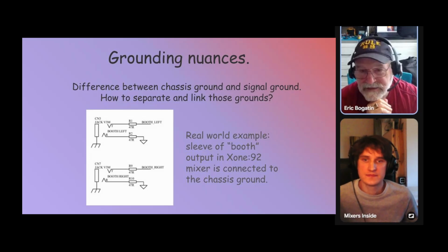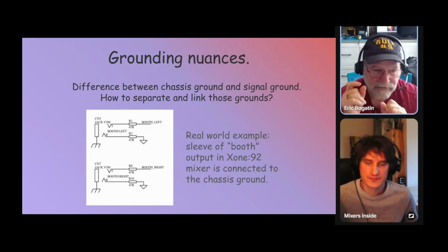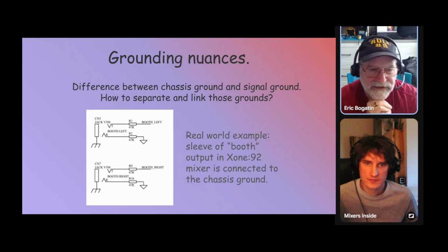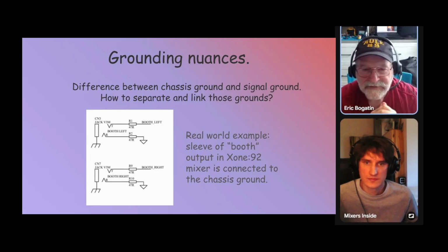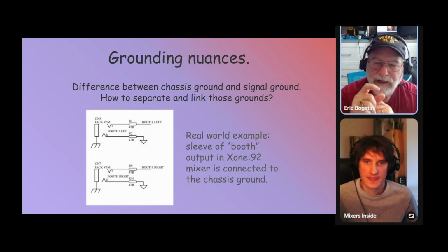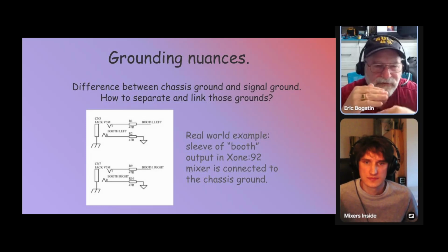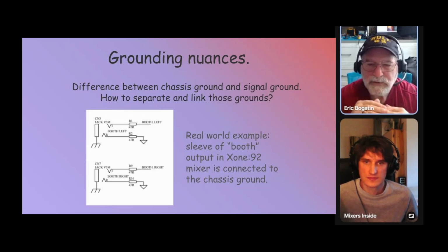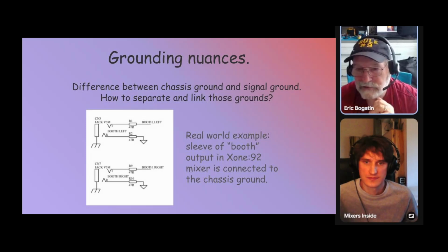And so the fix to that, if you're going to do that and have a single-ended plug going into your chassis from the microphone into the chassis, the fix for that is don't use a single-ended amplifier, use a differential amplifier. And that will subtract off, that will isolate that little bit of voltage noise there may be between the chassis ground and your local ground.